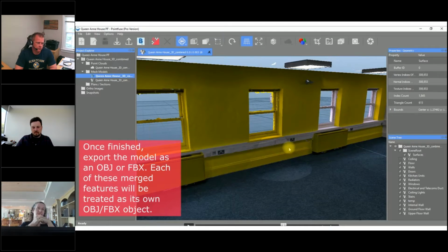One of the other big pros is just size. Typically, when we're dealing with point clouds and you talk like, oh, we've got a terabyte of point cloud data, that can probably be represented as 100 gigs of mesh data. If you've got 100 gigs of point cloud data, that's probably 10 gigs of mesh data. A 10x reduction in file size is a pretty common number that you hear. So you lose some fidelity and accuracy, though, like you said, Aaron.